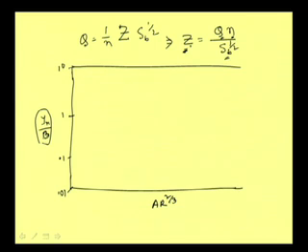So, what is its dimension? We can write L to the power 2 by 3 for this R, that is the length parameter, and then it is L square. So, this will become L to the power 8 by 3. So, its dimension is basically length to the power 8 by 3. To make it non-dimensional, we divide it again by b to the power 8 by 3, and this becomes non-dimensional. Now, on this side we are putting A R to the power 2 by 3, that is the section factor, divided by b to the power 8 by 3.